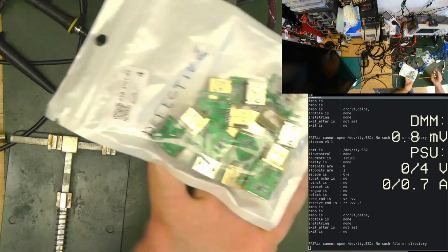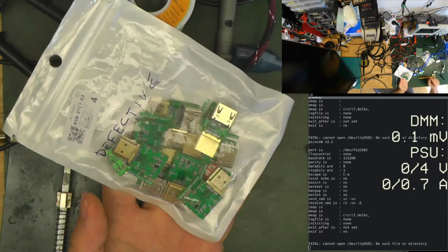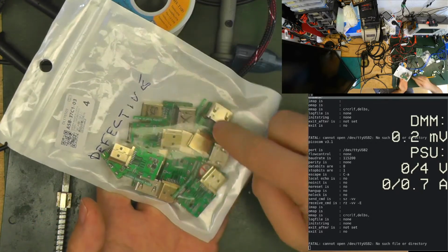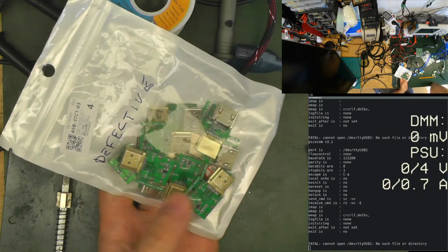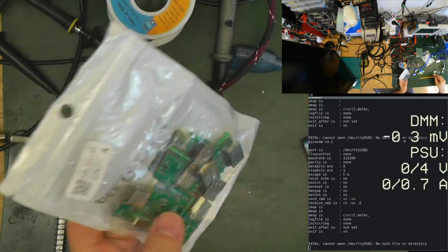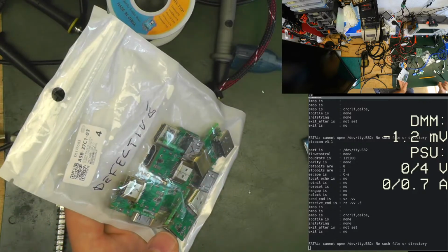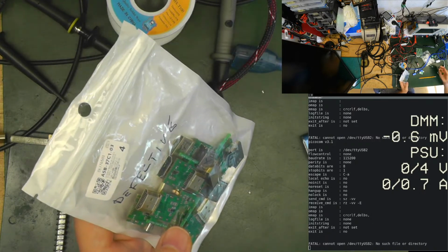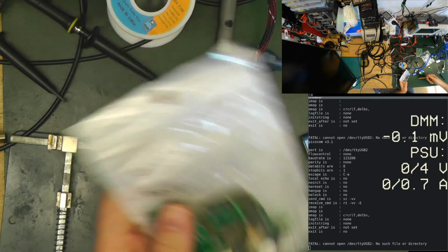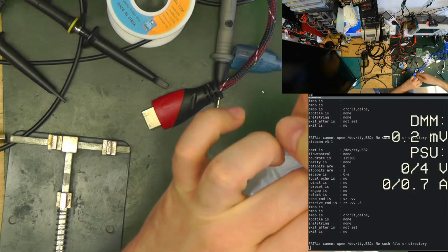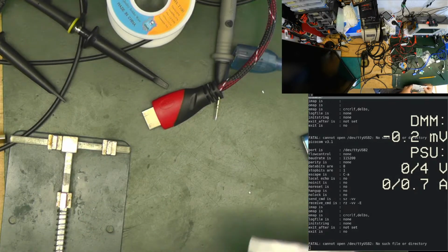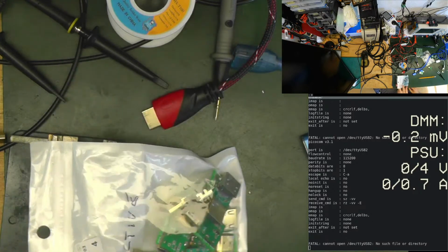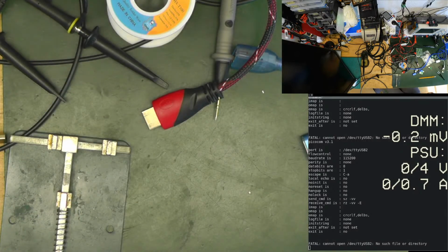So I did build more of them, but the solder paste was old and it created shorts under this HDMI connector. So I had a lot of defective HDMI firewall version 1. That's a shame. C'est la vie. This quality test passed. These are not quality test passed. Yeah. So solder paste, don't. 6-month-old solder paste, don't use it. It's too bad.